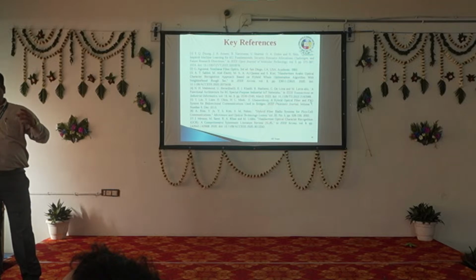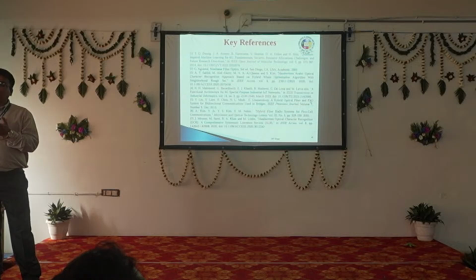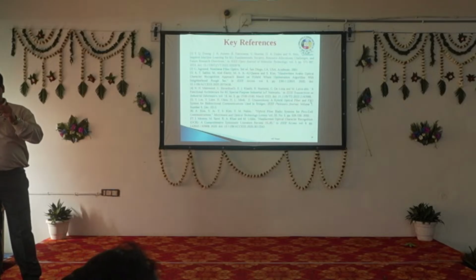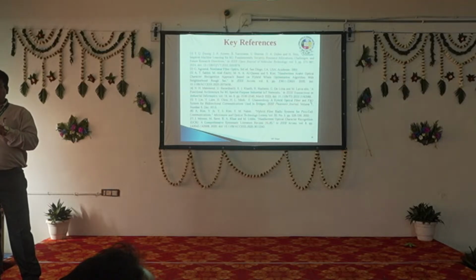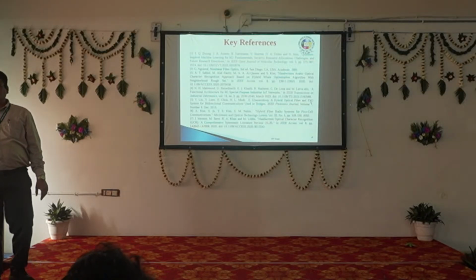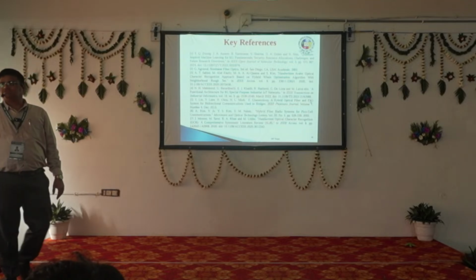When you are talking about full duplex, for achieving that we use different types of diversity, like frequency diversity. For example, I am transmitting at 1550 nanometer and receiving at 1552, 1553, a different wavelength. Then definitely the interference will be less because we are using a filter. By using the filter, we are able to distinguish which is the transmitter and which is the receiver. Yes, please. Any other questions, please?